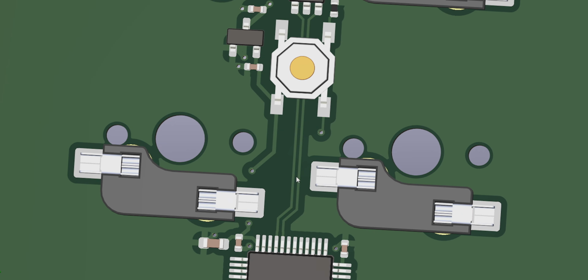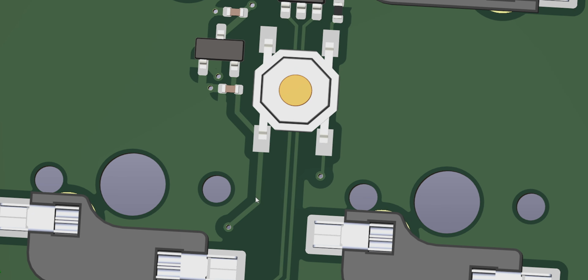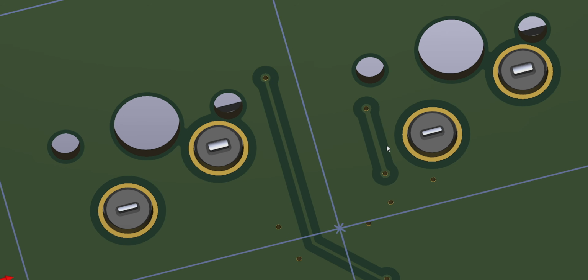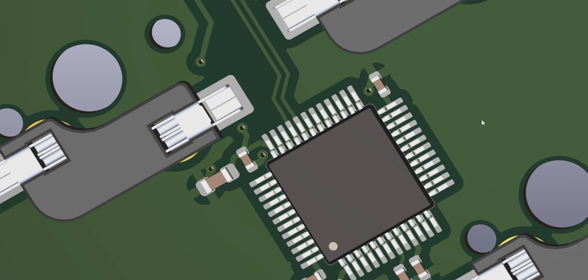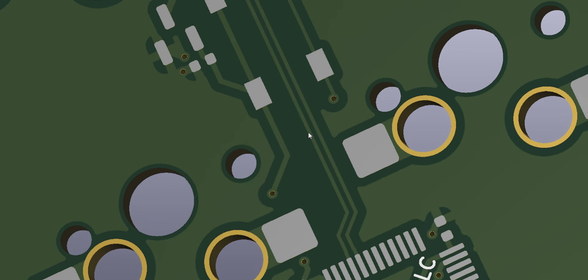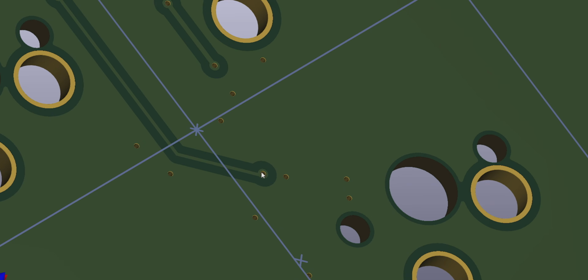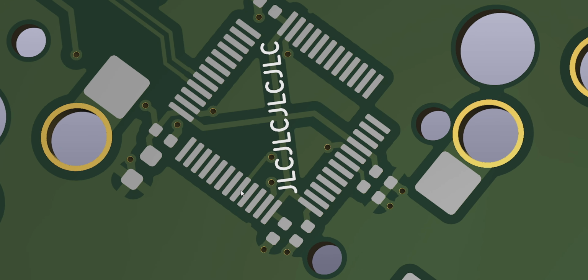If I jump into the 3D viewer, you can see our traces coming down from here. These are our data lines running into the MCU. We have our voltage line feeding off here. This is 3v3, feeding behind here. If I jump onto the other side, you see that's where it jumps, and then that feeds into the capacitor. If I hide our components here, we have our bootloader button feeding down into a via, flipping onto the other side, running down, and flipping back over right here. Finally, it feeds into the reset button right here. So that is the overall idea of the PCB editor.